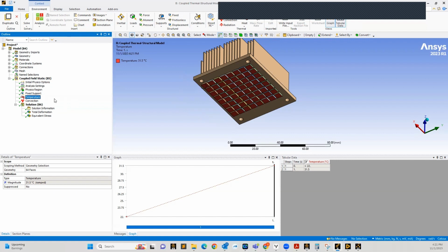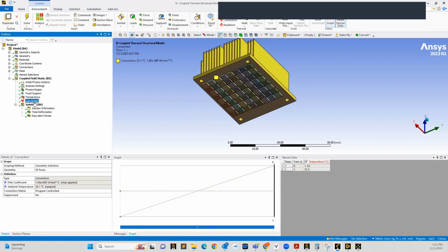So whenever you have a heat source, you have to have a heat sink so that heat can dissipate from your analysis, right? And you don't have everything just be the same temperature. And in this example, what I'm using to define my heat sink is this convection boundary condition. If I change to standard units, you can see here that I'm essentially defining natural convection, about 10 watts per meter squared Celsius, and my ambient temperature is just a little bit warmer than room temperature, right? I think I said all of these in US units, which is why these are kind of decimals.